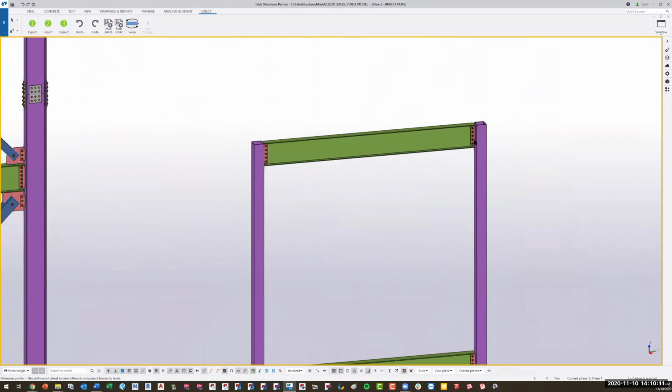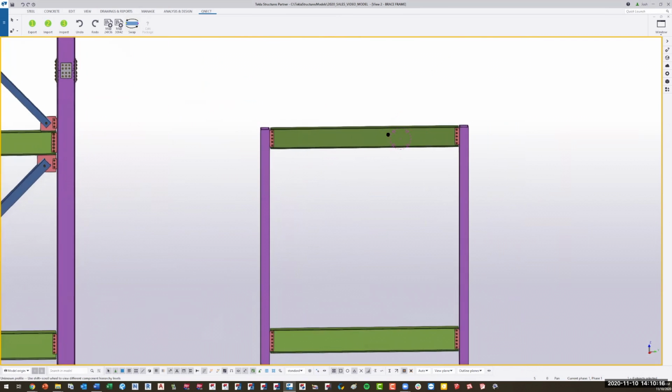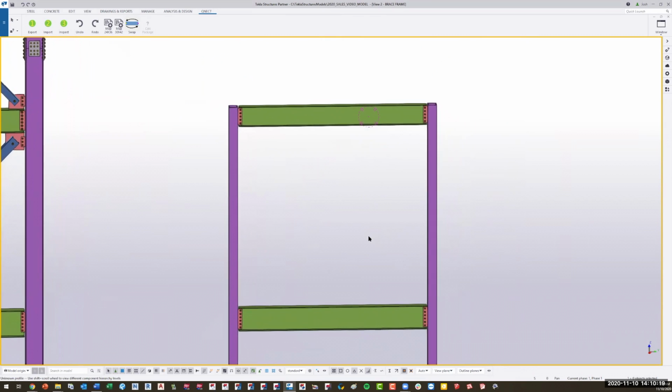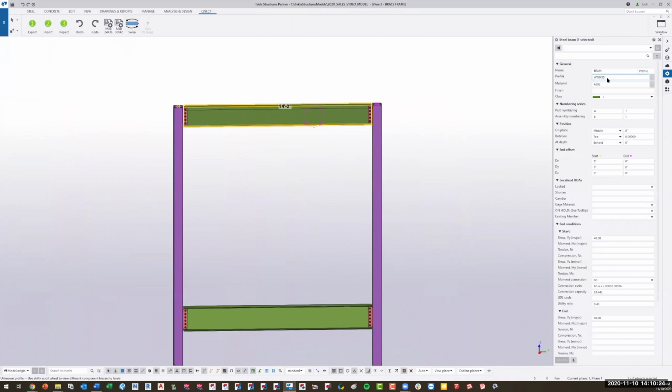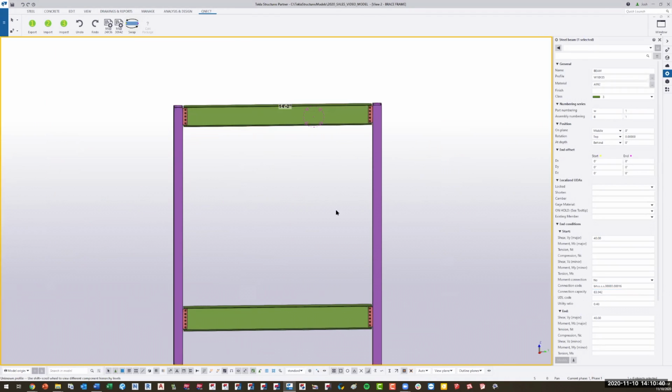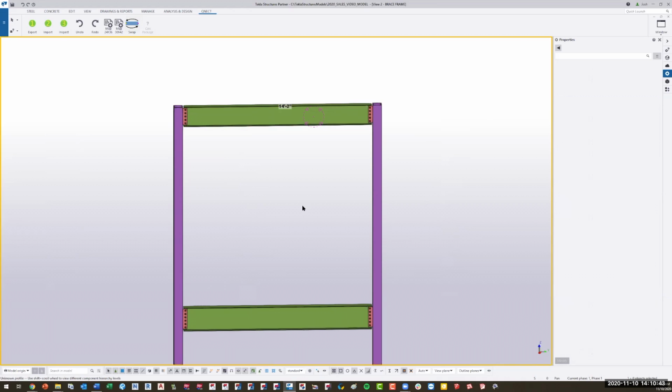Let's go ahead and go over to the HSS columns over here, because let's try and make these more efficient, more friendlier for the shop, cost effective. So what you see up here, you have an 18 by 35, and you have 5 bolts on either end. And then you come here and you have a 2150. You have 6 bolts. Okay, it's worth 102 kips. And this one, these connections are worth 83.94 kips.